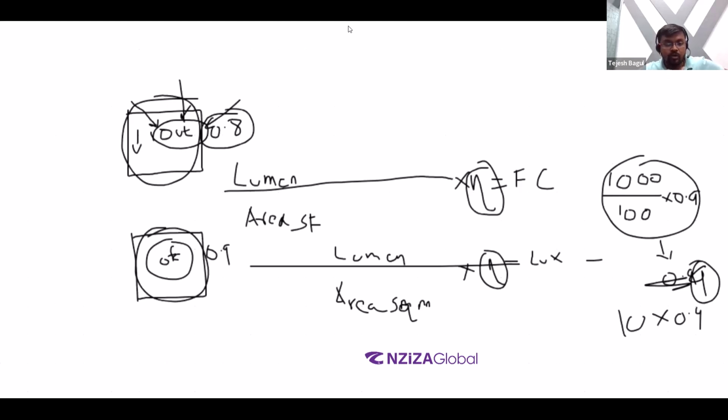If it was a parking lot, then of course you would have to reduce the efficiency for the light fixtures. Now, going back to our project that we had left, when we talk about a patient room, we need to properly adjust the light fixtures to achieve a foot candle level of minimum 50. If it goes higher, that is fine, but make sure you try to be around 50 foot candles.